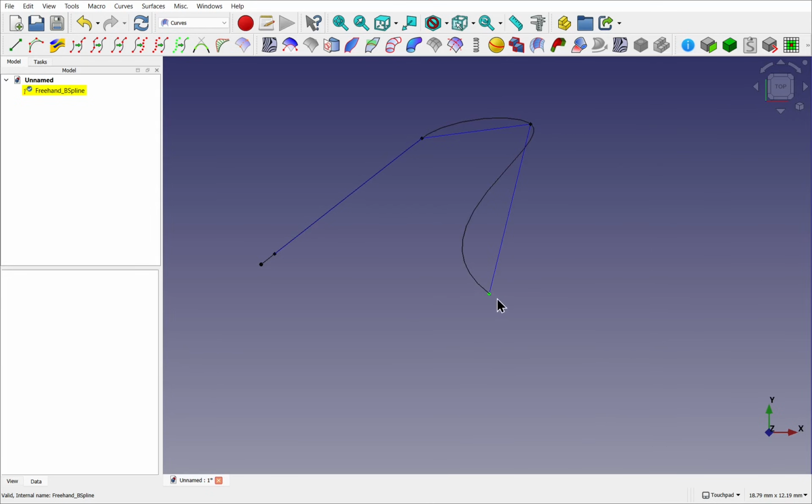We can restrict the axes that these points move upon. So if I was in between views, let's say about here, I can move this point in this direction, which is moving it along all the axes, depending on which viewpoint that I'm within.